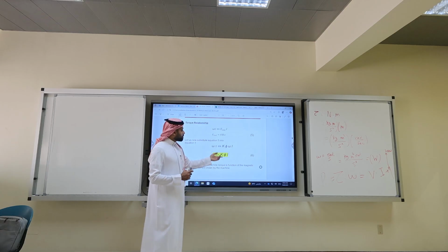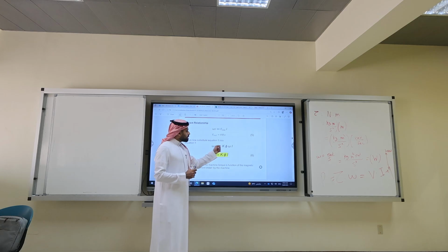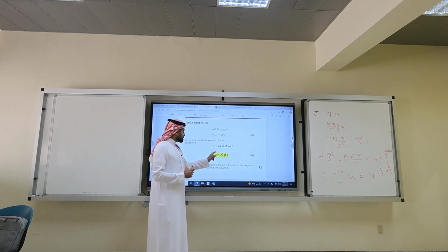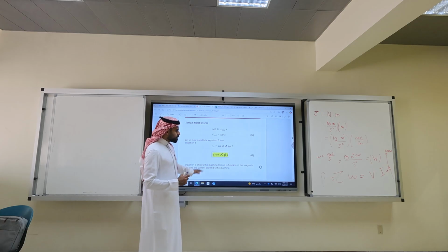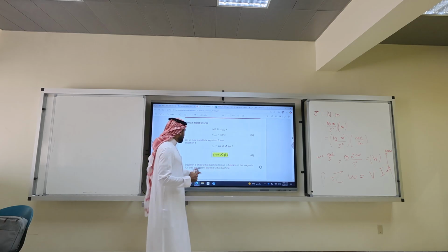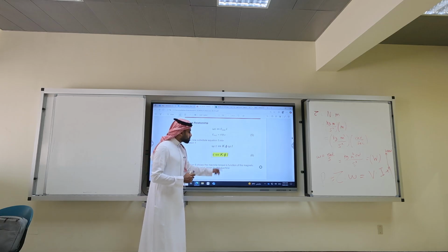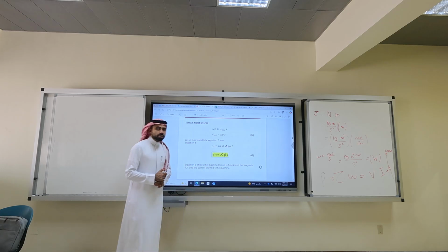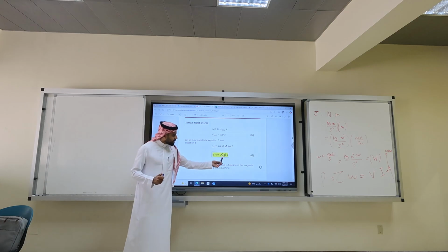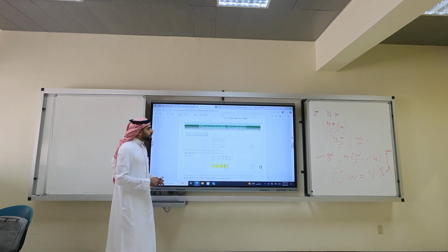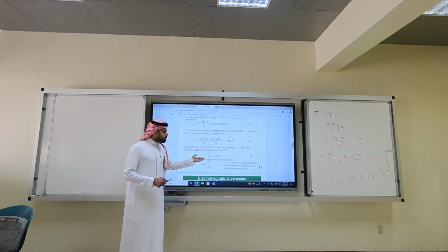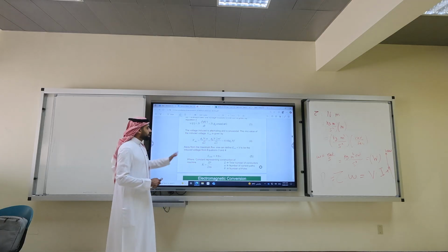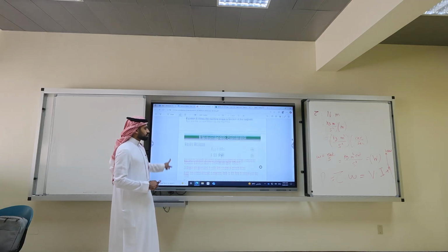That is the key, because the omegas will cancel. The only thing I'll have is K times the flux, which is, again, the induced voltage. The omegas will cancel, and I'll have this equation, where equation 6 shows that the machine torque is a function of the magnetic flux and the current drawn by the machine. So to increase the torque, I need to increase the flux, or increase the current, or increase the constant, which is a parameter of poles, conductors, and the current path. We will define these quantities later, okay?